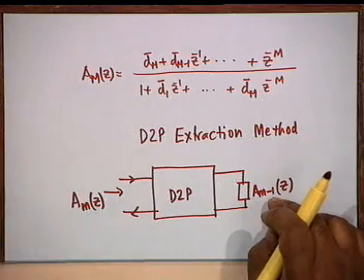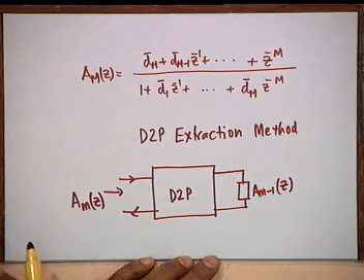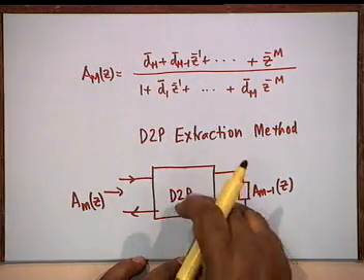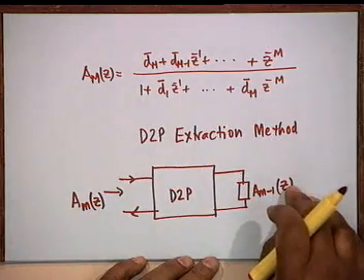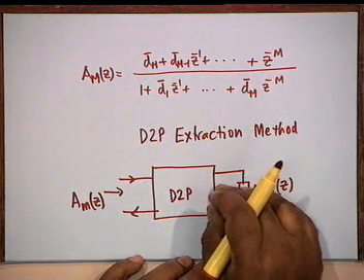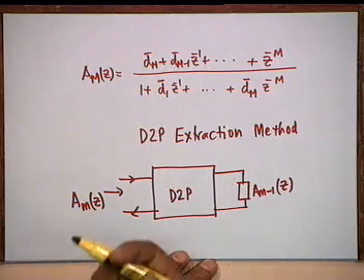So can we apply that procedure to get an alternative realization of the IIR all pass filter of any order? It turns out that the structure that you get has been quite well known in statistical signal processing, and the structure that you get is a lattice, and for some reason lattice has been found to be very suitable for VLSI implementation. That is, a DSP chip you can implement in VLSI if the realization structure that you use is a lattice.